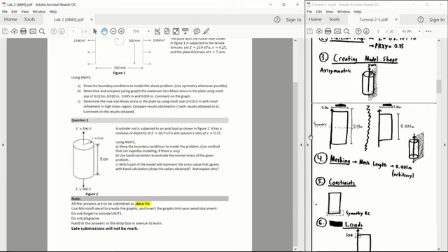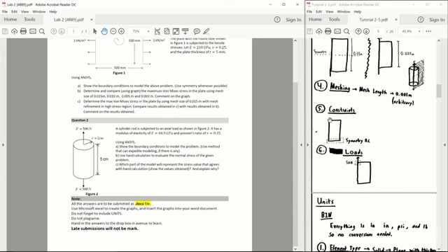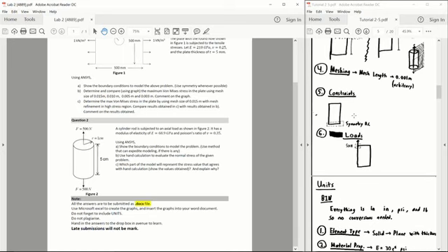In terms of meshing, no mesh size is specified in this question, so we can pick any value that we want. So I'm just going to choose an arbitrary value of 0.001 meters, just because I think it will best suit this model, but the choice is up to you. Next, in terms of constraints, since we are splitting the object in half along this axis right here, we're going to have to put a symmetry body constraint.